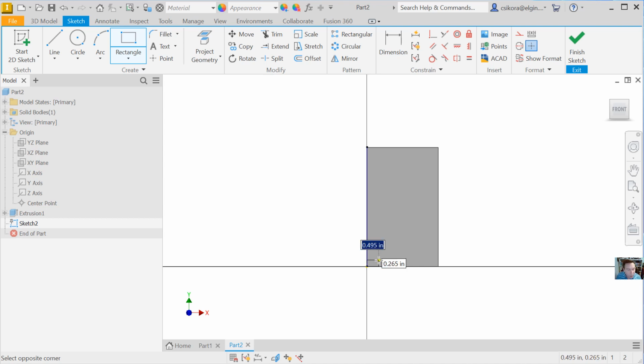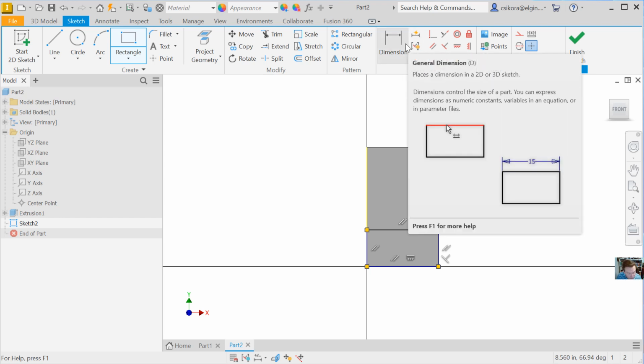Okay, so I'm going to click there and I'm going to drag this over to the right. Now you can see it's locking in at 3 inches. I could actually stick with that. I could click on the edge, but then I lose the ability to add the dimension for the height. But let's go ahead and do that. When you click on the edge, it creates a relationship to the right side, so both will expand. If we change that 3-inch dimension on the lower part, both of these will expand. You can break that just by typing in a dimension for the 3-inch for the second entity.